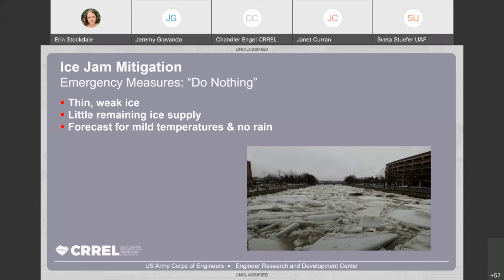So if those sort of conditions exist, ice can melt out thermally, get weak, or maybe just go down or be gone when the river stages start rising in the spring. So it's important to assess how severe the situation is, even if there is broken up ice on the river, if it's not causing major problems. It's important to weigh that scenario with putting people at risk and equipment and stuff to try to do something if there isn't necessarily an acute flood risk.